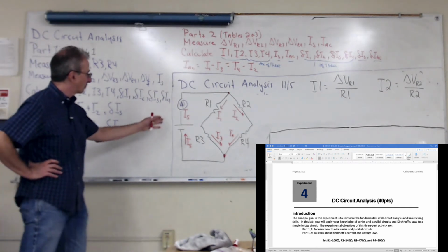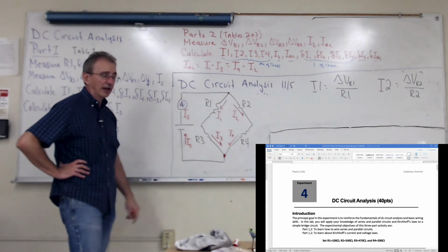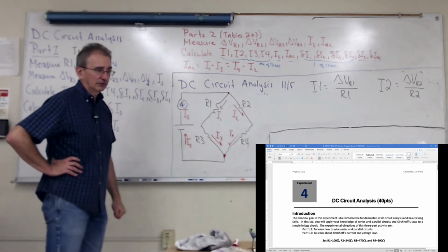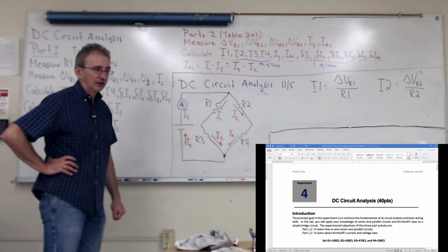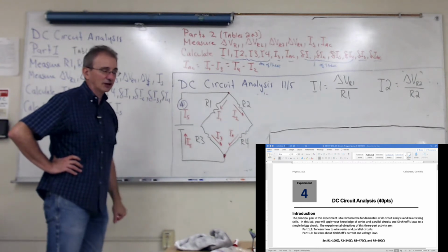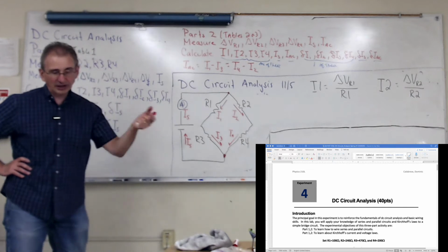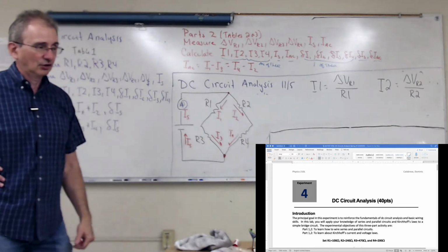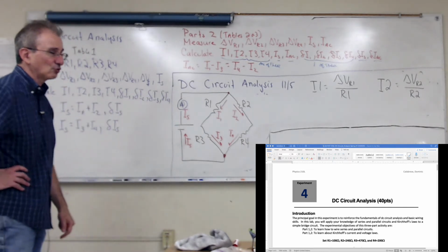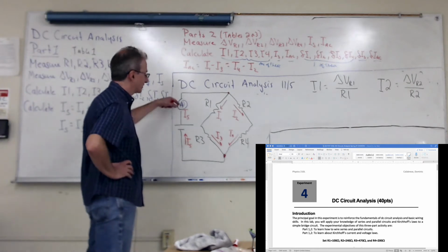And you should use the appropriate current scale. You don't want to use too big a current scale or too small a current scale, because you do want to get a lot of sig figs, but you might not want to get too many, because if you get too many, then the resistance here is large.